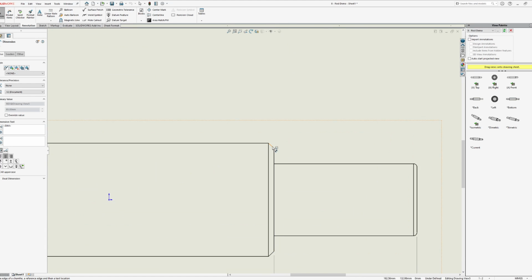Back to what I was saying before, we always want to make sure that our chamfer has a reference point. I might say, well, I know that this is the edge of the chamfer, but it hasn't created anything. That's because it says, okay, sure, I know what the length of this is going to be, but what should the angle be with respect to some specific other edge?